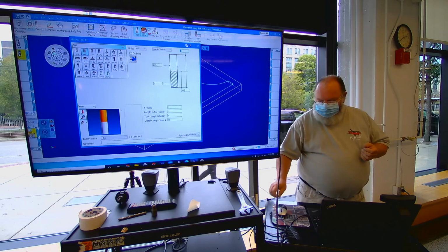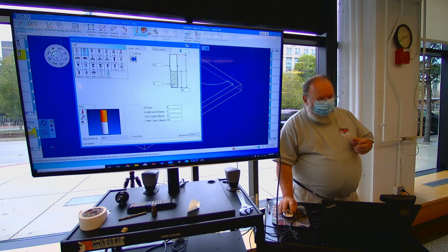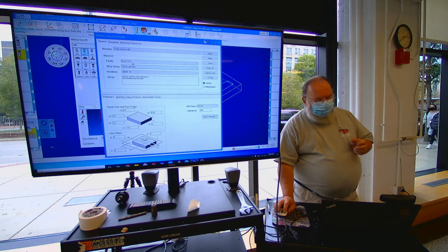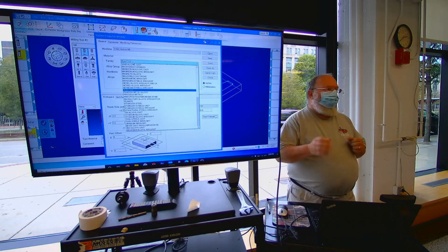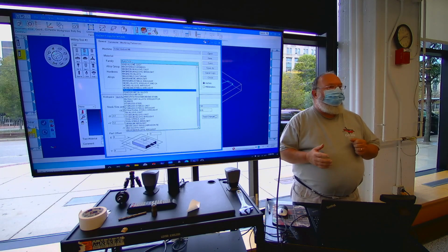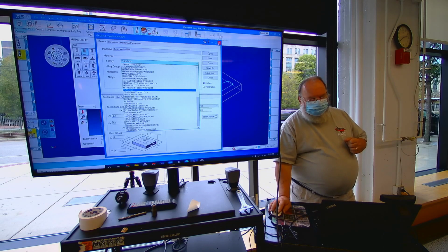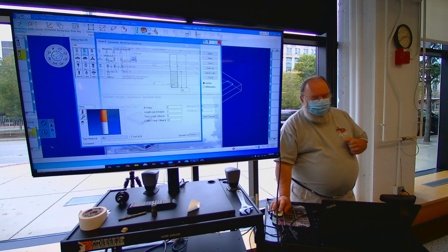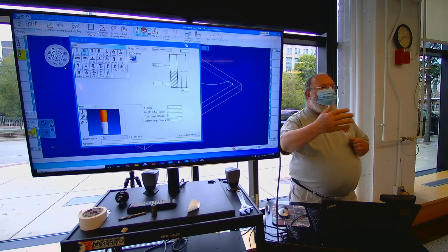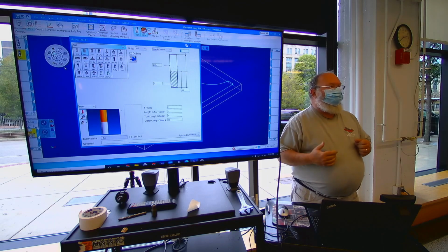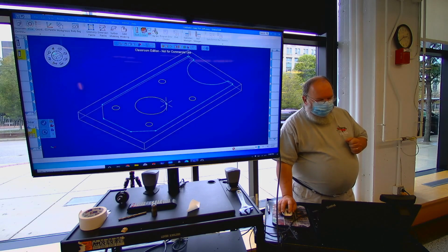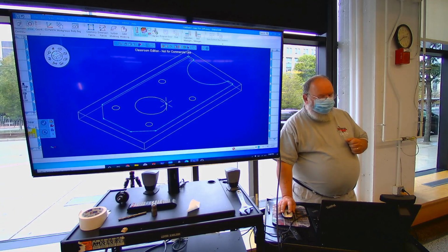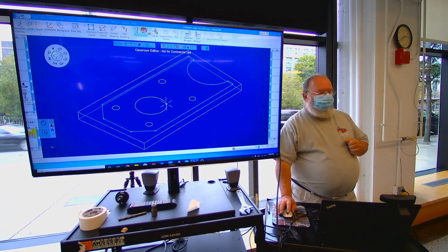And that has a bearing on the other thing that I didn't discuss in this. This is an actual material database. So I selected plastics, but it has a ton of materials in there. And based on your cutting tool material and the number of flutes, it's going to bring back suggested speeds and feeds. All right. Tool number 9 is a thread mill, and tool number 10 is a 1/4-20 tap.